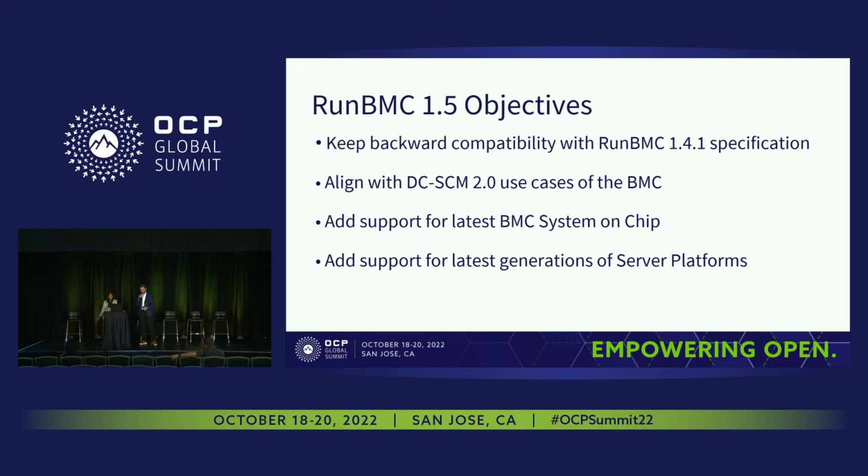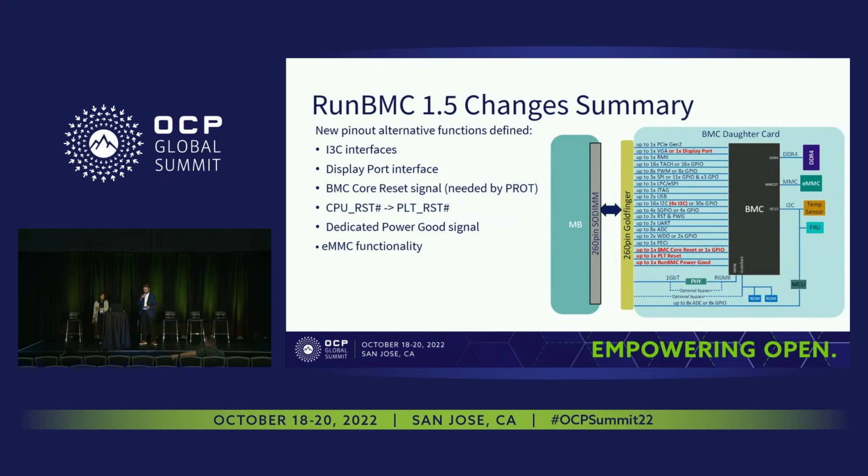All right, so we have 1 minute for the v1.5 updates only. The major objectives are to keep the backward compatibility, because this is not a major update. This is a minor update of the spec, so we just want to update it so that it's usable with new BMC SoC designs. I'll just walk you quickly through the majority of changes. We add I3C support, we add DisplayPort support, which was not supported previously. All the dedicated resets that found their way into dedicated pins instead of just GPIOs are being defined here.